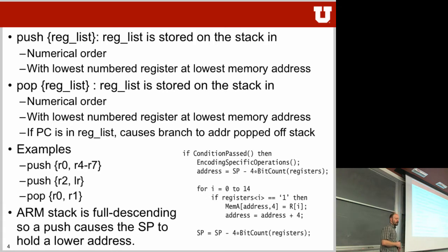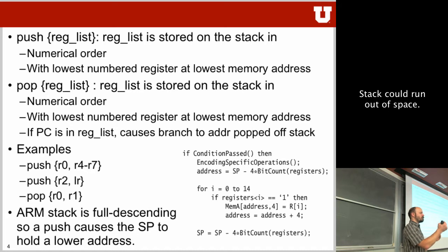Another important note is that the ARM stack is full descending. So if you push something into it, the memory address becomes smaller. Yes? Question? No? Okay, sorry. The memory address will become smaller, right? So it starts off at a higher number and then starts to go down, down, down. What's dangerous? What could happen? You could run out of your space, right?